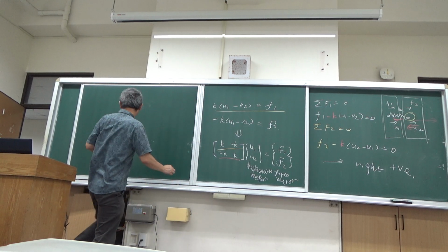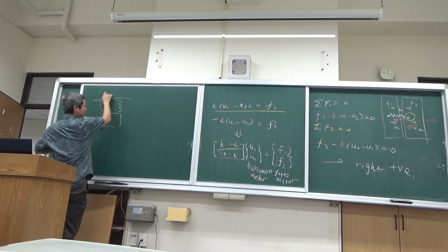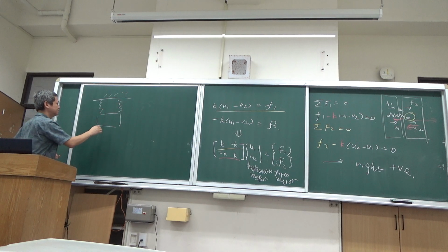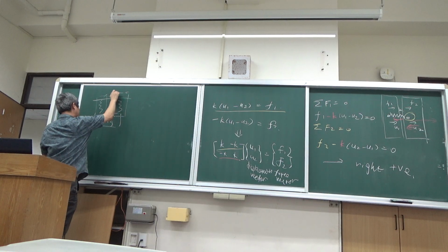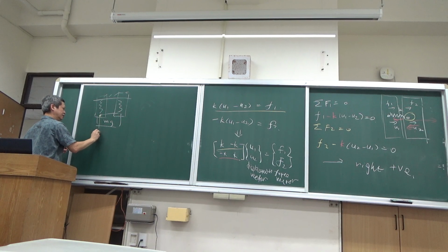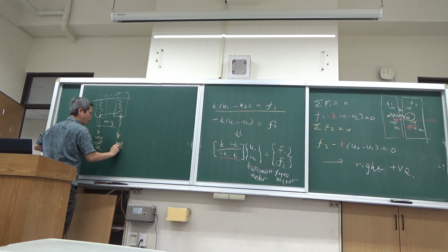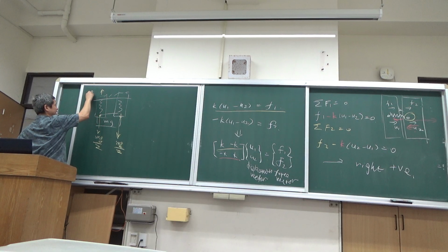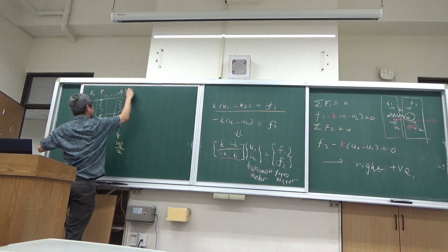So when you try to handle the question here, two springs support one mass, or one bag. You can see this mass as mg. If you now focus on the two springs, the external force is going to be mg divided by 2 on both nodes. And then you have the reaction forces, let's say R1 here, R2 here. No, this is not 2, this is R3.